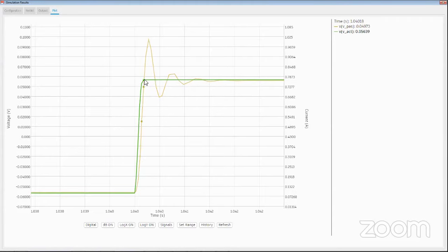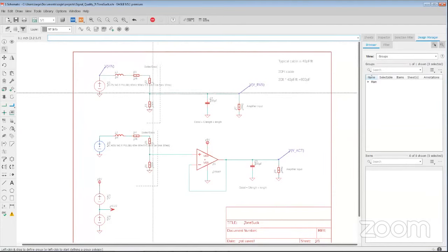The longer your cables get or the more capacitance they have, the more you're going to see your high end roll off. In real life, you don't get this type of oscillatory behavior because you would have a tone control and you would have those things coming into play. But you would see that the active circuit would preserve the quality of your signal much more than a passive circuit, because you have this high impedance interacting with this higher capacitance due to the length of the cable. And the more cable you have, the more they're interacting.